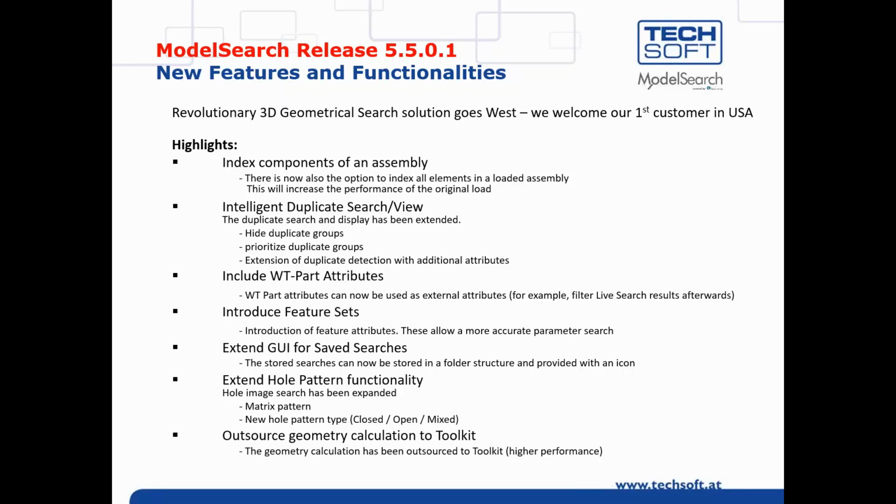That is something which runs in the background. For the initial installation, we can use CAD workers working in parallel. Right now Windchill supports up to 8 parallel CAD workers. So we use that process, and we can bring down the time it takes to generate the footprints.